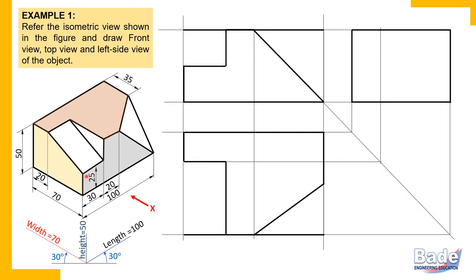Now we'll measure 25 millimeter on front, this is front side. From bottom, parallel to height, 25 millimeter vertically you should measure. You may measure independently. And here already we have measured 25 millimeters. Remember, this edge is common for these two surfaces. Since this surface is already completed, the 25 millimeter height we have already measured here. So you may project it in this manner. I prefer measuring 25 millimeters independently here. Okay. So we have drawn all principal edges and now this non-principal edge.